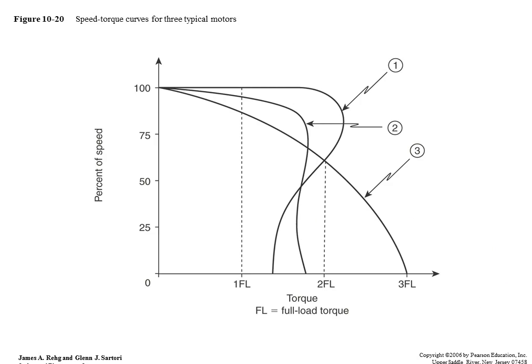This is speed torque for a normal three-phase motor application. With all three phases going, you have a nice curve, fully loaded. If you drop one of the phases, then you're a single-phase motor.